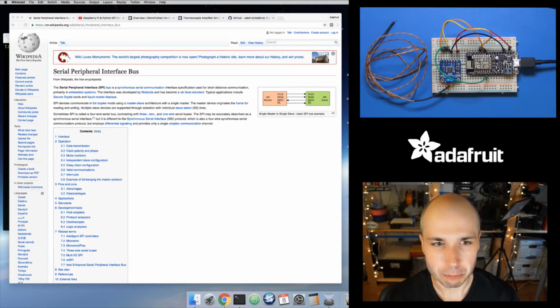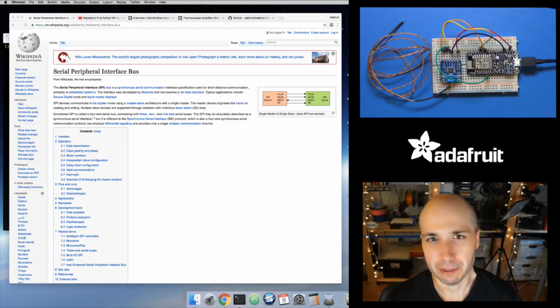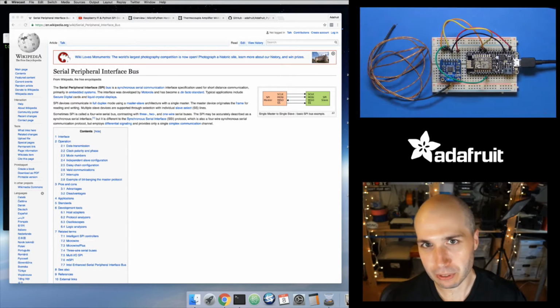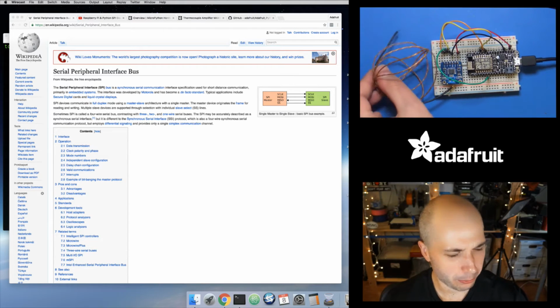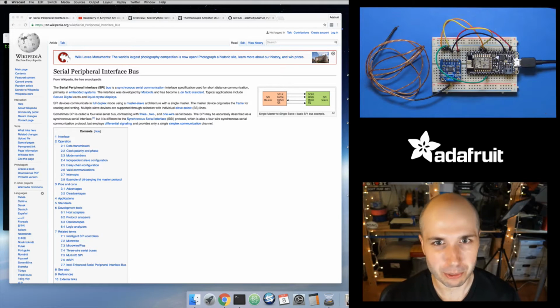They're very nice because they have a really wide range. You can get all different types of thermocouples. They're fast to react. There's not a lot of metal here to heat up. So if you put this into boiling water, which I don't think this one's waterproof, but you can get waterproof versions, it'll instantly tell you 212 degrees. Put it into ice cold water, and it'll tell you, okay, this is like negative 20 degrees or whatever. So really nice, fast reaction, super useful temperature sensor.